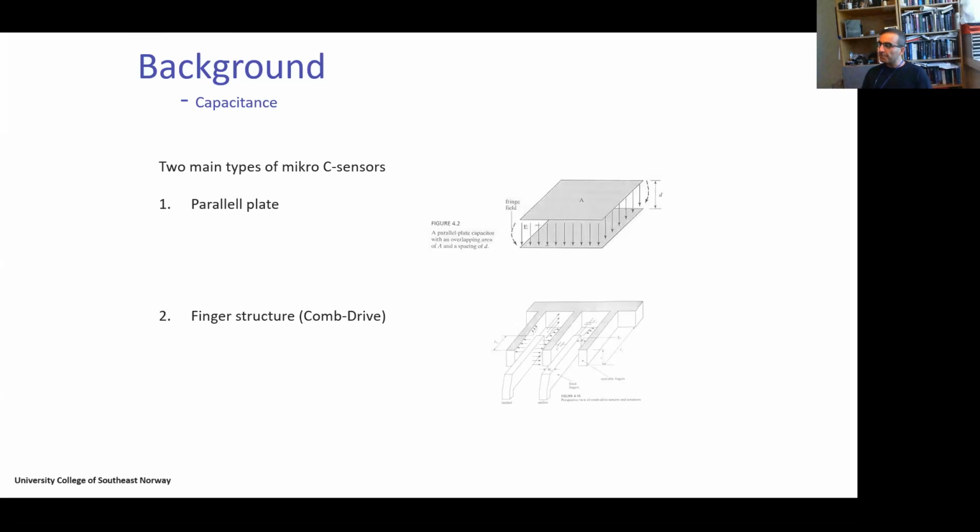So in microsensors and microsystems, we normally have two types of capacitive sensors. The parallel plate sensor, again, the "parallel" is a mistake, I forgot to correct it, it should be one L, but the parallel plate sensors, as I showed you the principle. They are often used in pressure sensors, where air pressure presses a thin membrane, the top layer, for example, and this thin membrane is bent toward the bottom plate, and then you have a change in capacitance.